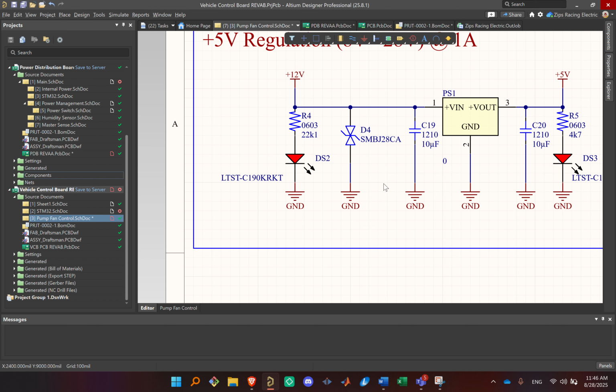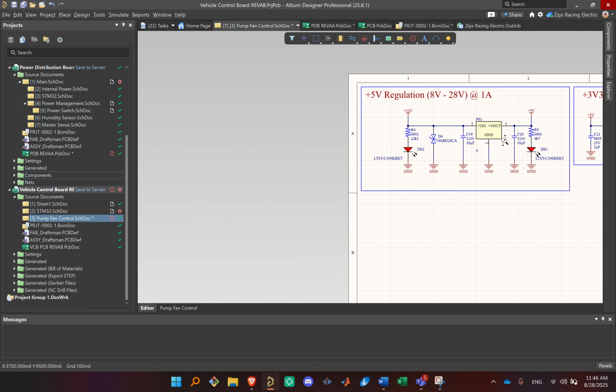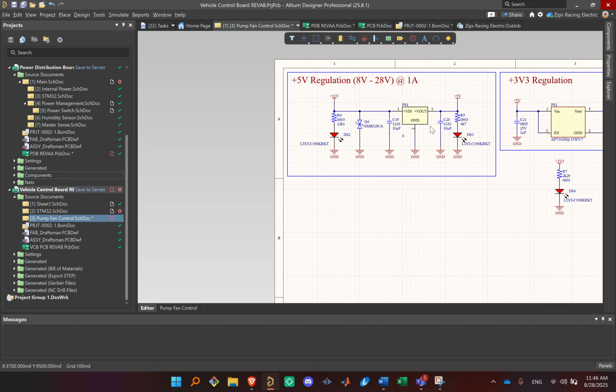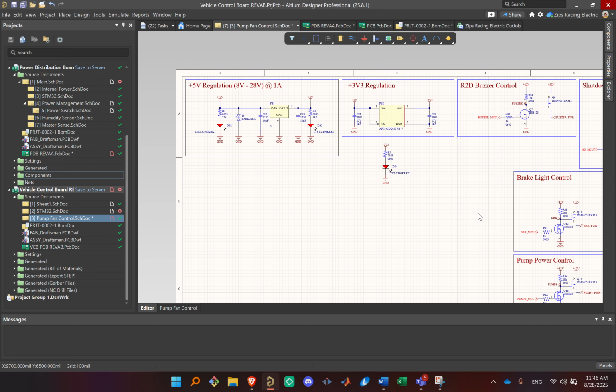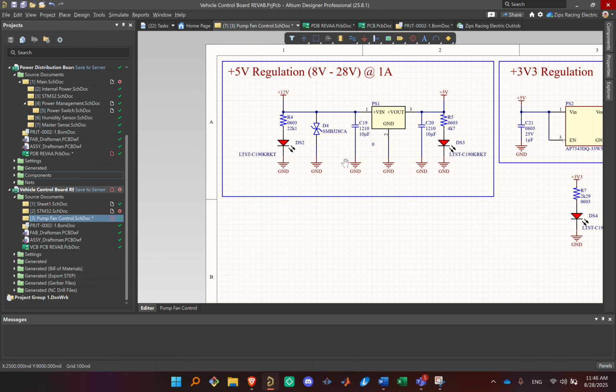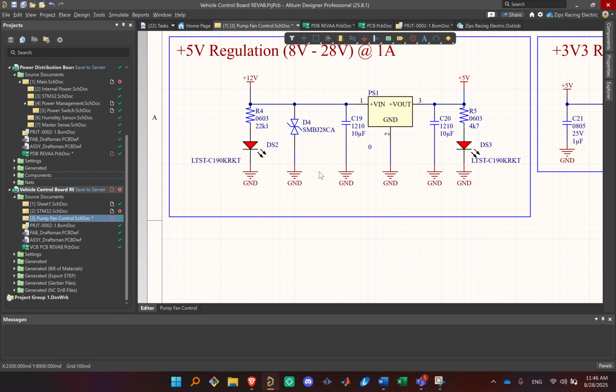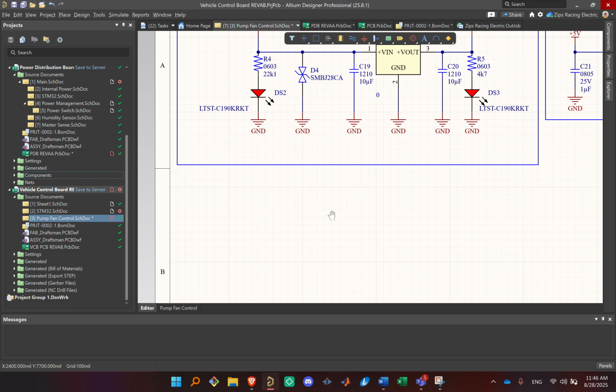So basically, if you plug in power backwards or apply a voltage that's too high, it'll blow and it'll protect everything in the circuit. We do that on basically any circuit board that interacts with the main car battery, just because people in the past have plugged in stuff backwards and caused a little bit of havoc. But it's just a good precaution to have, and it's good engineering practice to have that sort of stuff.